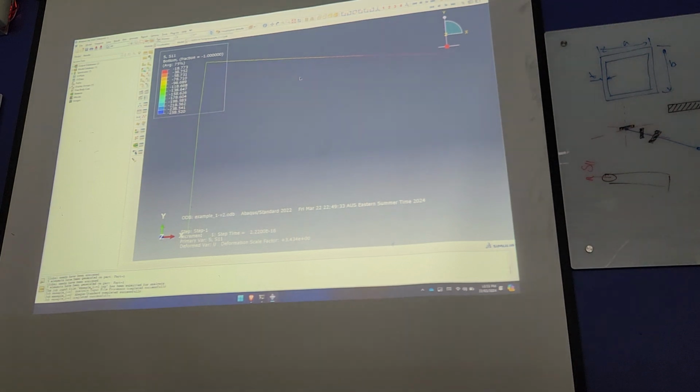So you need to go, okay, just write beam section, truss section, both of them. Then you keep the beam, then truss section, then truss. Then from here, you need to input one cross-sectional area. So you need to assume a cross-sectional area.